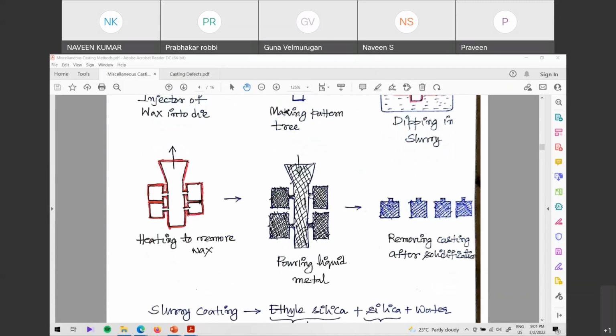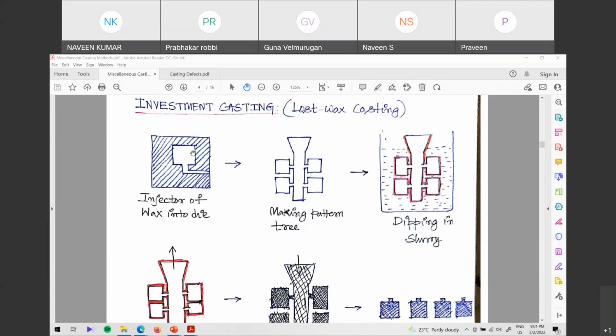After that, you cut off the parts that you wanted to use at the end. And this gating system is your waste, because this goes under the volume of the gates, and this is the volume of the casting that is very important. So yield might be less here. So this is the procedure.